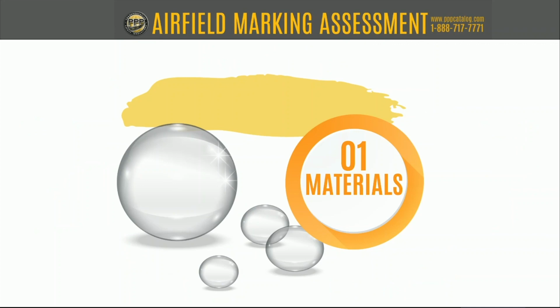Each airfield has its unique needs and an environment around it, so you have to take that into consideration. And following up on what Mike said, there are only a few type choices, type 1, type 2, type 3 paint, or type 1, type 3 beads, but there's a lot of brand choices. So oftentimes type choices are far easier than brand choices. Be sure to look for that, and get references as well.